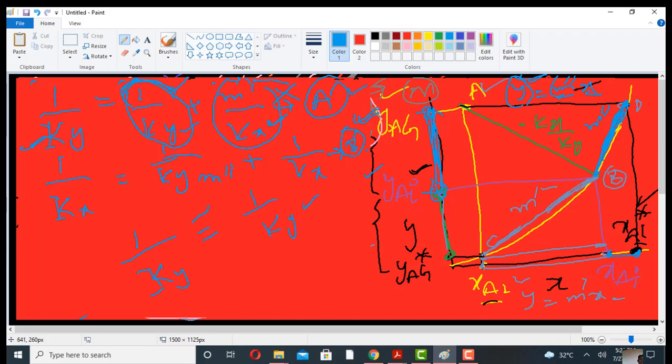Similarly, if the gas is not soluble in the liquid, then very high resistance will be provided by the liquid to the gas transport. So this term will be negligible and this term will be very high. So 1 over Ky will be equal to m divided by kx. So this is all about the individual and overall mass transfer coefficient.